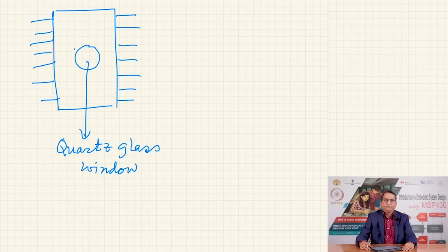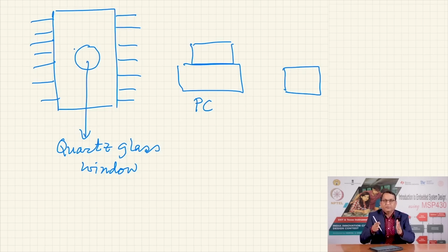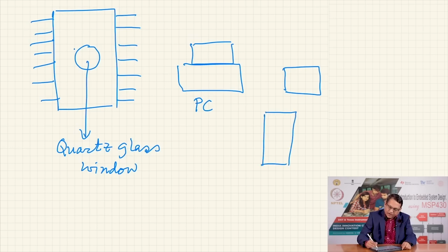So they would use an EEPROM, first erase it, and then put it in a special system, a special programmer connected to your PC through some protocol. On this programmer you would have a socket with a lever, where you raise the lever, it opens up the pins, you drop the EEPROM into the pins of the socket and then you press that lever. That special socket, something like this, these were the pins of the socket. This was a special socket.